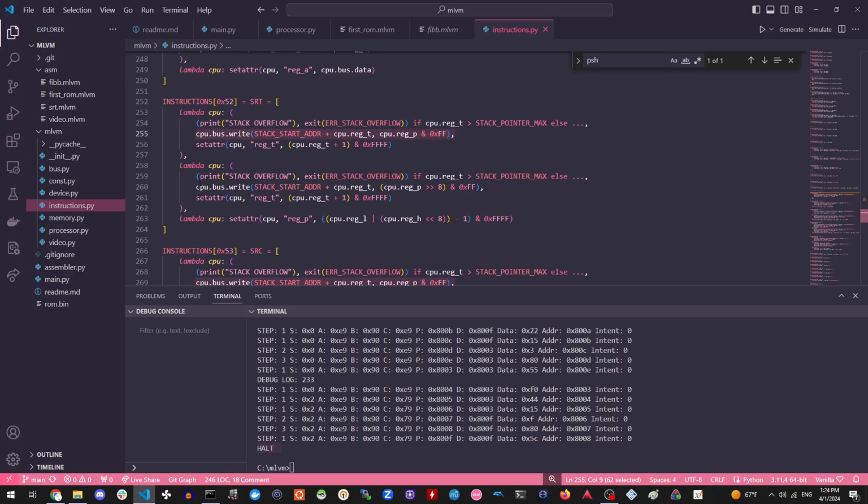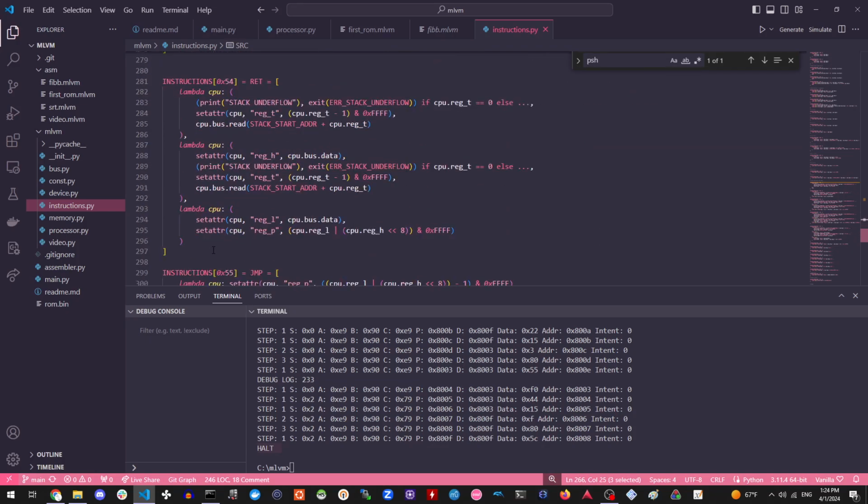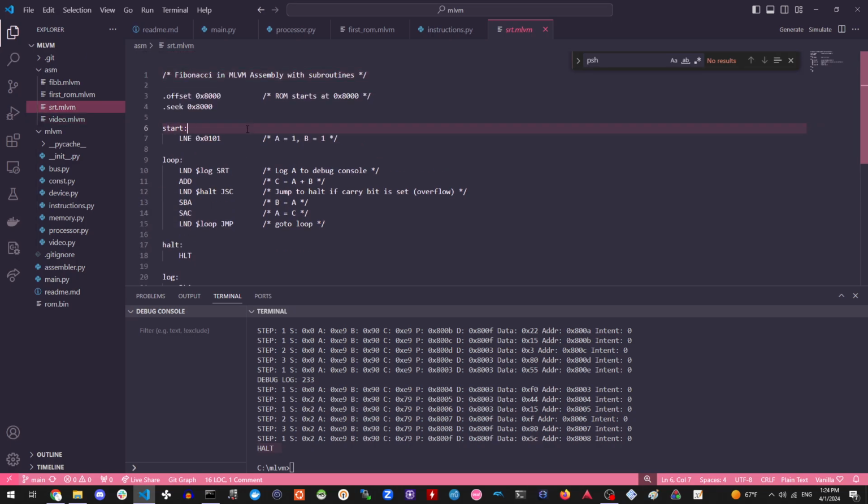I write the program counter to the bus, and then I just execute the jump. And then I also have subroutine if the carry bit is set, and then obviously when you have a subroutine, you need the return function. So this return function just pulls those two things off the stack, then jumps to what you pulled off the stack. Basic subroutine and return.